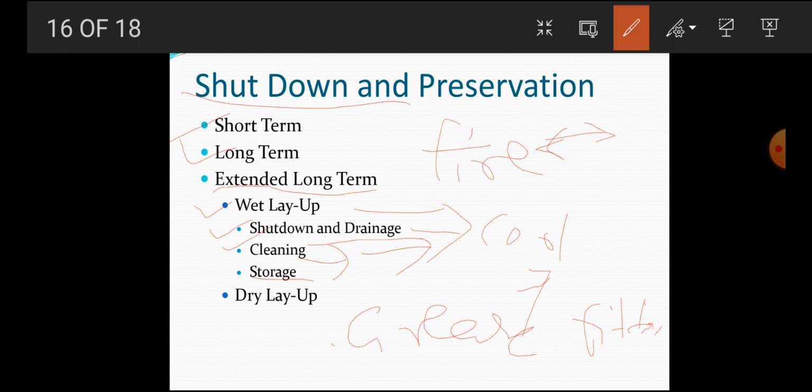Then we need to close all the handholds, use new gaskets, then close all mud leg openings, then close blowdown valves, then close try cock or pop off valves, close fire side of boiler, all openings, connect burner, open oil lines and turn on all switches.